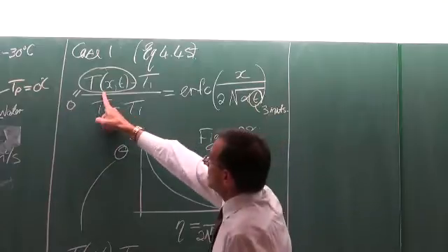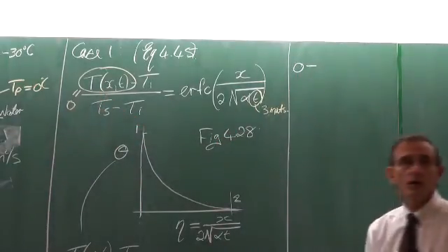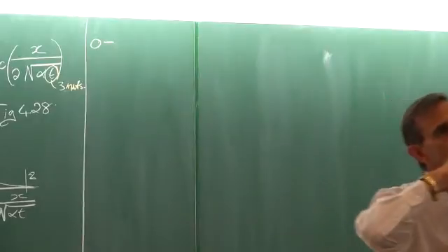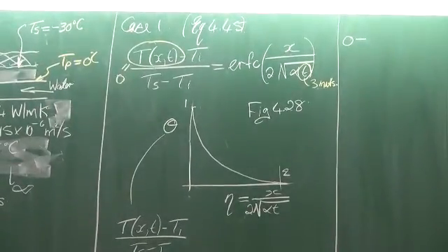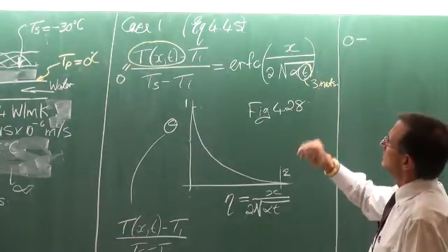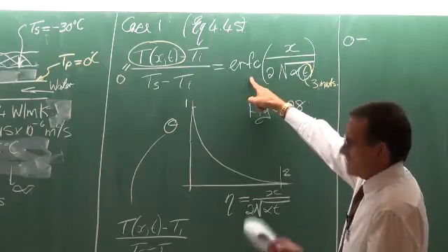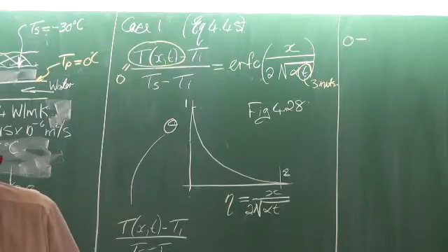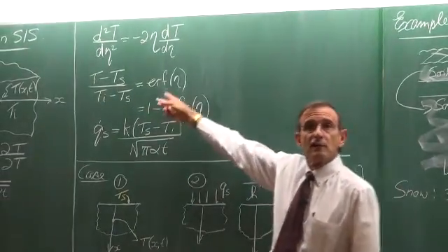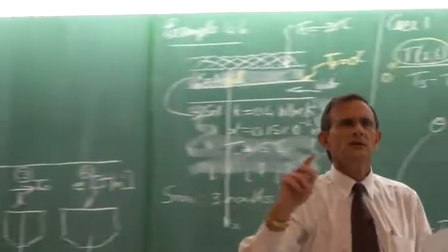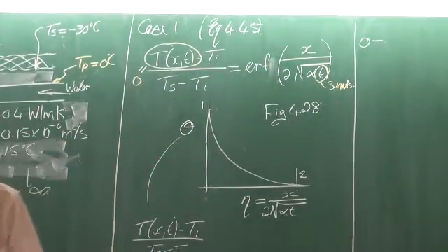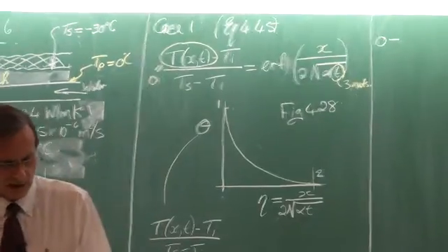Okay, so the temperature we want to know after 3 months at a depth of h. Yep, question? That's ERF, shouldn't it be 1 minus ERFC? This one. 1 minus ERFC. Is it correct? You've got it like that, all of you? In terms of the error function, you can also write it like that: the error function, or 1 minus the complementary error function. You've written the complementary one. Ah, okay. Yes. Okay, thank you. Now I think it should be the complementary one.